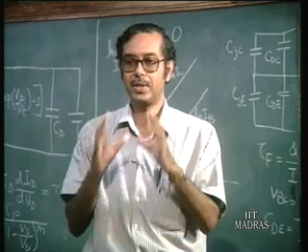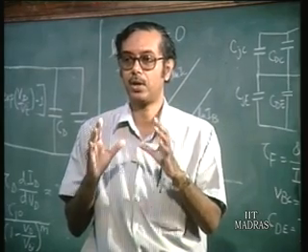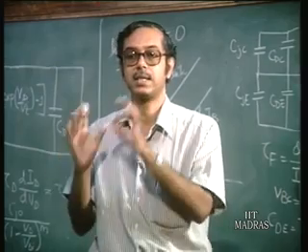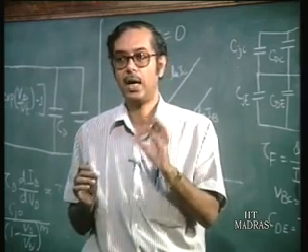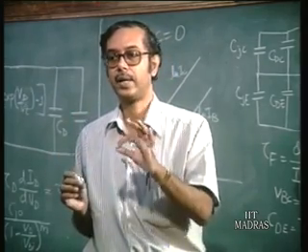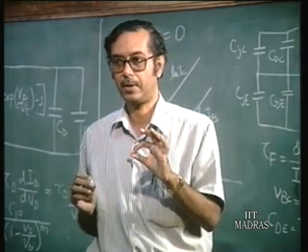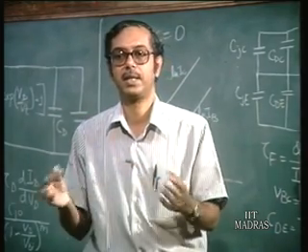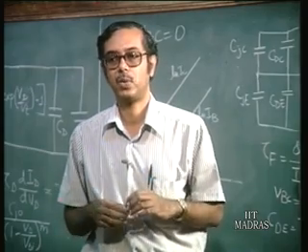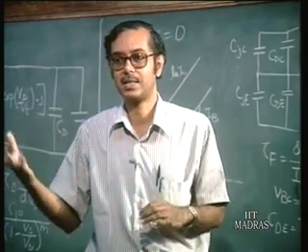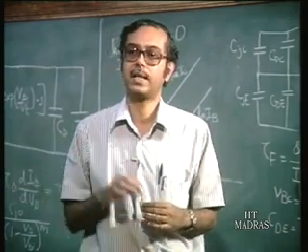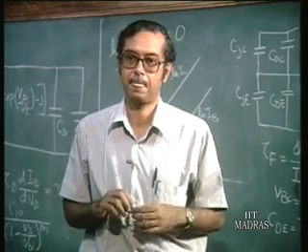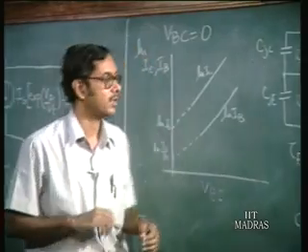Once you discuss a model, it is very important to know, because the model is defined in terms of certain parameters, and it is important to know how to extract these parameters so that you can use that model in a proper fashion. And you are not dependent on the default parameters provided in any simulator, because they may be wide off the mark, because they may be just some representative values and not the exact values for the given circuit, for the given transistor.